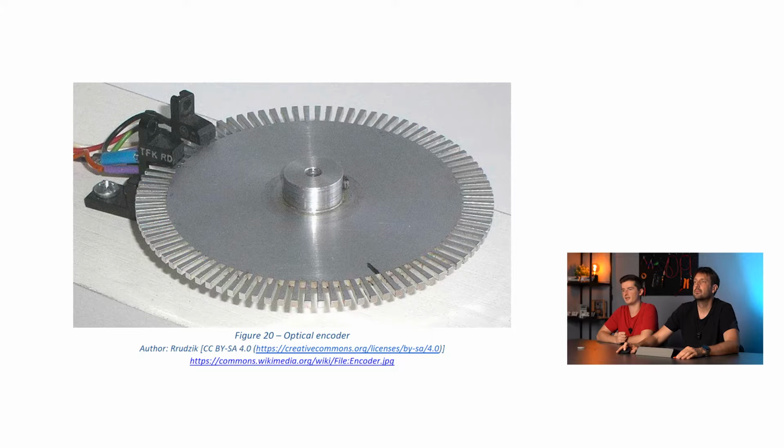If we take the previous example further and put several markings on the motor axle instead of a single one, we can use them to measure the amount or the speed of the rotation. To do this, we have to make a disc on which opaque and transparent lines are alternating. Usually, they paint black lines on a transparent material, for example glass or plastic. Then, mount the completed disc on the rotating axle and place the optical gate sensor in a way that the disc is rotating inside the gap of the sensor.